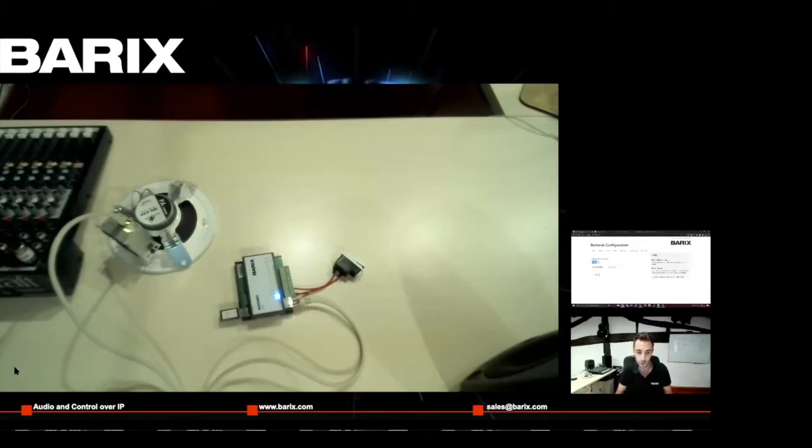So I will switch on the application now and I will set the server address, 105. So I submit. And now the client is running and the server should have identified my Barionet device immediately. Indeed, I can see that it is now active. When the device is connected to the server, it announces its capabilities, as I said before. So you can see here the GPIO numbers, 4 inputs and 4 outputs. The 4 outputs are the 4 relays of the device.